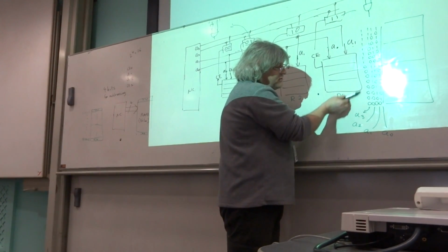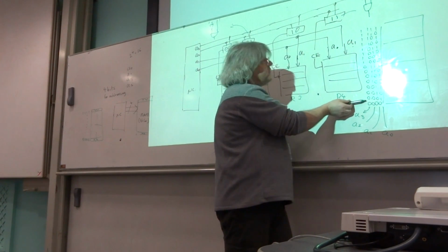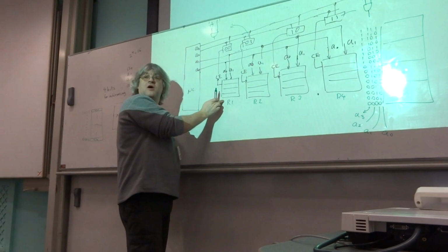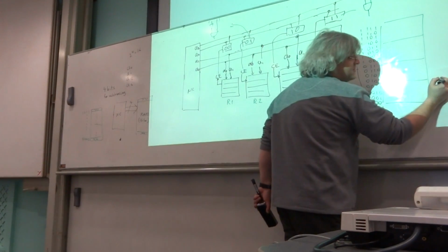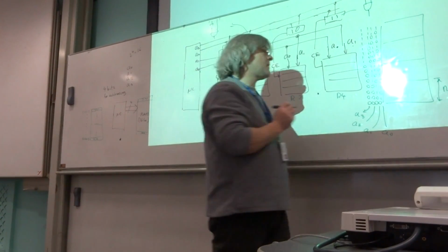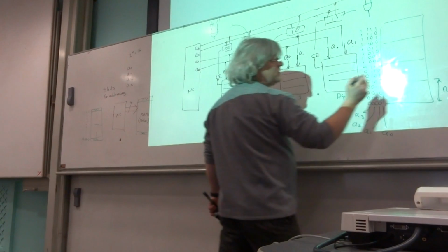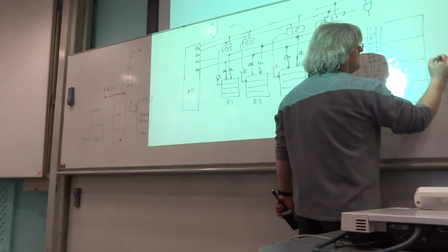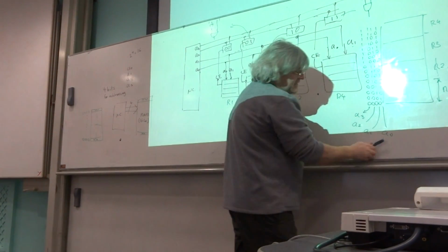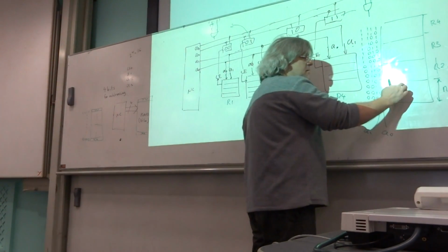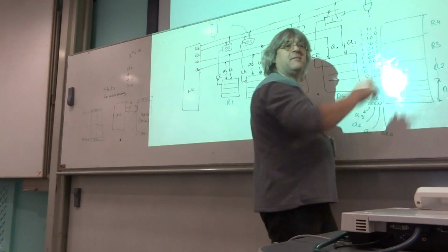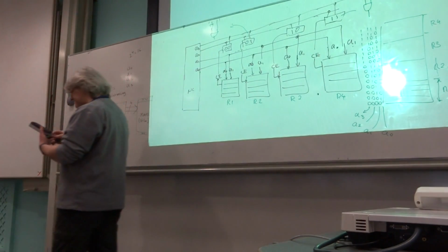If you look in this region, both A2 and A3 are low the whole time. Well, that would correspond to when R1's awake. So those 4 locations would be locations where only R1 is awake. The next one here would only be where R2's awake. Here when only R3's awake, and here only R4's awake. The A0 and the A1 will actually be used to tell me which of the 4 memory locations inside R1, R2, R3, R4 I'm actually talking to at a particular point in time.